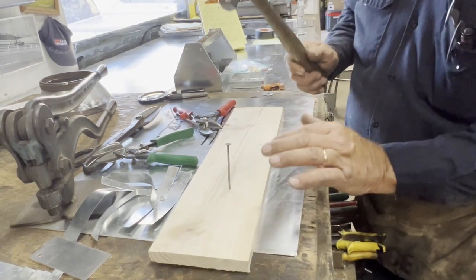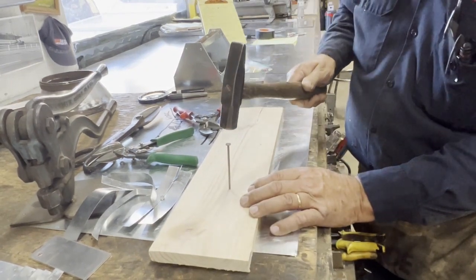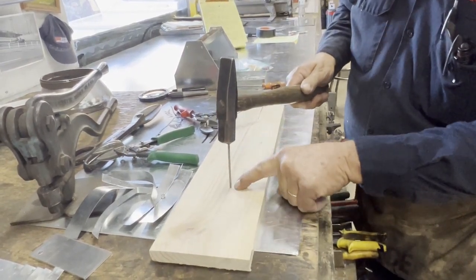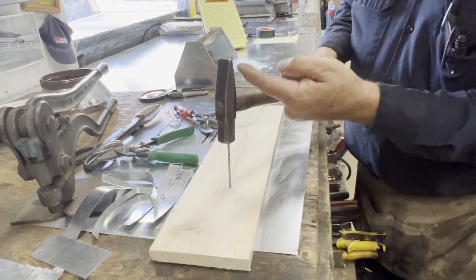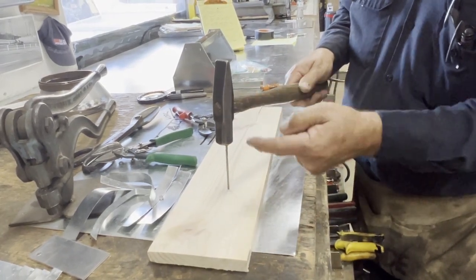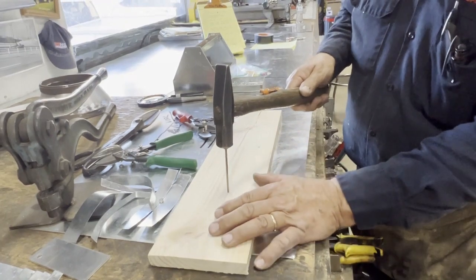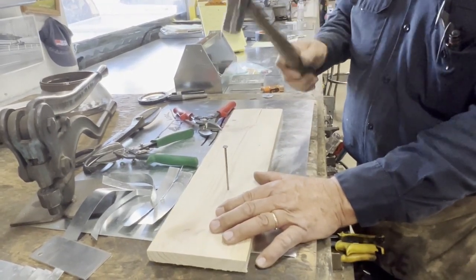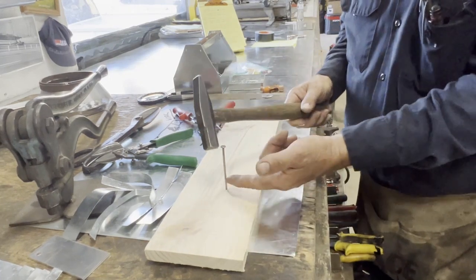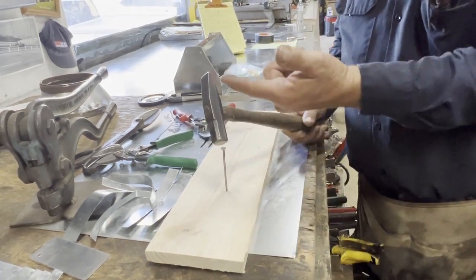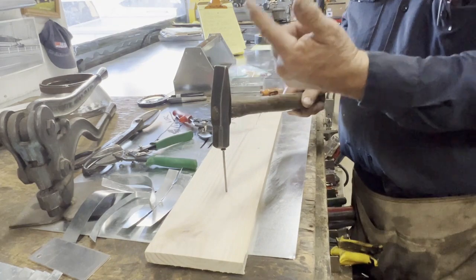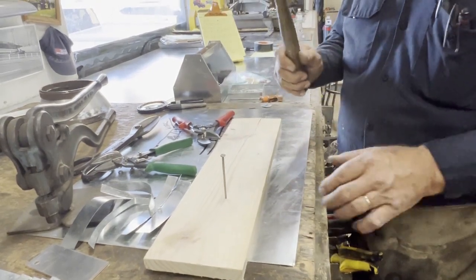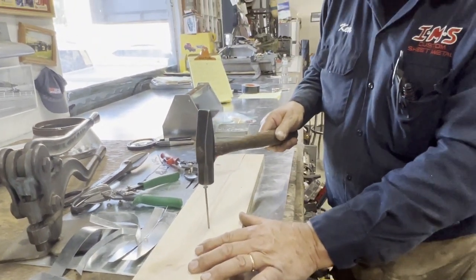Because imagine this. You hit the nail, move the nail into the wood, and as the hammer is bouncing off of the nail, as it will, if you work on your timing, now you're actually using that return energy to propel the hammer back and ready it for the next strike.